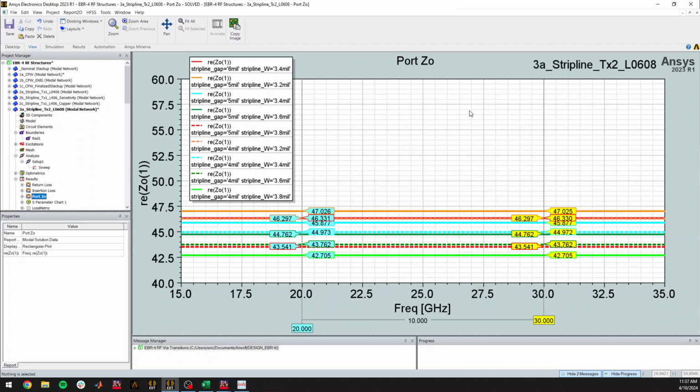We're looking to reuse the same stripline structure for all of our RF layers, not having all these unique stripline layers that needed to be accounted for and supervised and managed. It just made things easier from a layout perspective to set the same design rules for every stripline layer, that is. So, this is why you're seeing the performance is not dead on 50 ohms. It's somewhere around 45 ohms nominally.